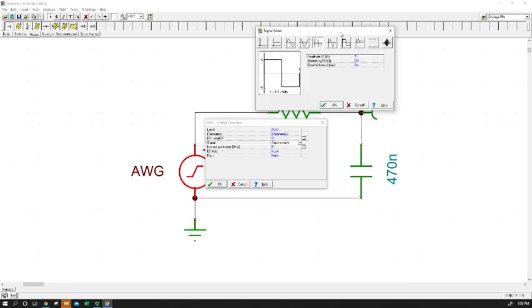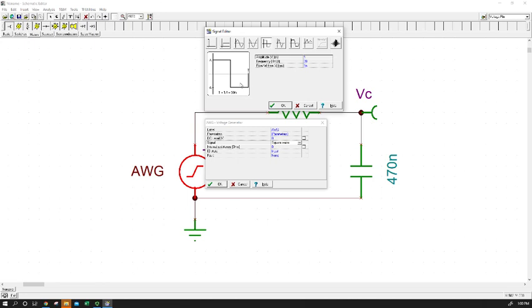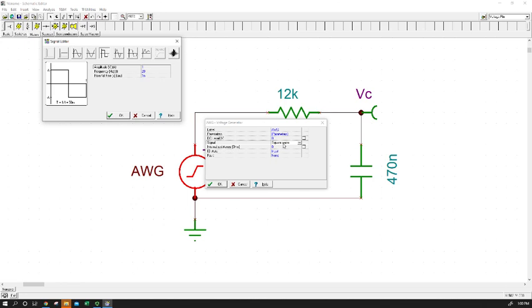I'm going to select square wave, and we have an amplitude of 1 volt, and I've chosen a frequency of 20 hertz. Now that frequency was chosen deliberately with a knowledge of the time constant that we already have for the circuit. So we can get our calculator out and take a look at how this corresponds. What we want to do is choose a frequency of our applied square wave signal that will ensure that on each half pulse, each half of a period, we'll be able to reach steady state before we switch the voltage and either start charging or discharging the capacitor.